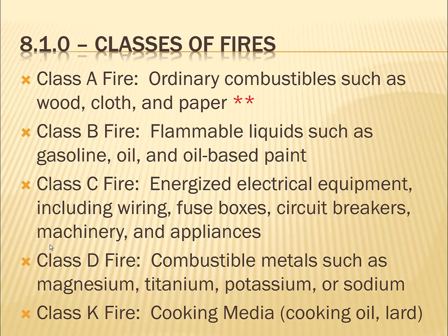They are metals. So the Class D fire extinguishers are yellow. The tanks are yellow, whereas the Class A, B, C fire extinguishers tend to be red. The Class D in yellow, and then they've got a label on there with a yellow star in there with the D in the center of the star. And there's a pasty material that comes out of a Class D fire extinguisher, where generally the Class A, B, C fire extinguishers that are rated for all three are mostly dry chemical, mostly baking soda, or something of that nature. Not baking powder, that's got flour in it, which would be flammable.